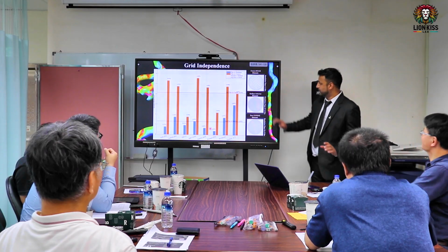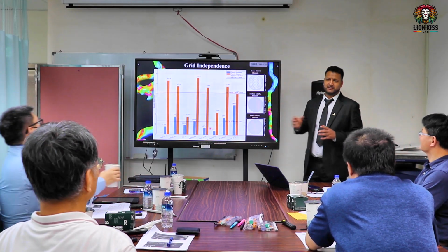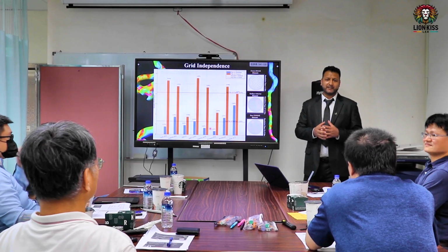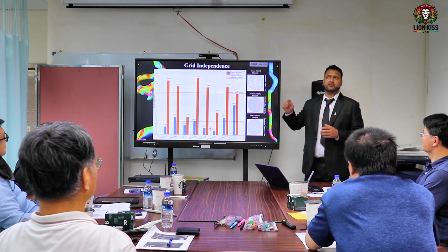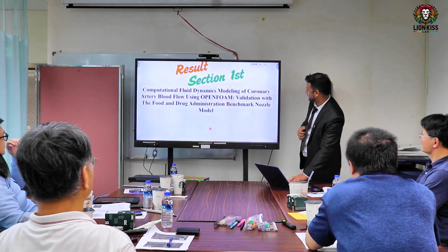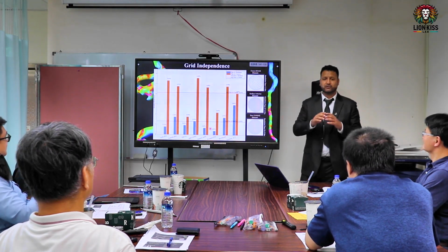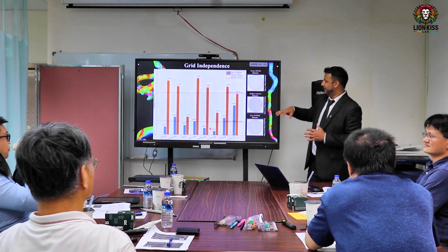Yeah. So basically, computational fluid dynamics depends on the meshing. If the quality is good, the result is better. Like the convergence, we check the Courant number. In one table I show the Courant number, and it should be less than 1. So we check according to the Courant number and other parameters.